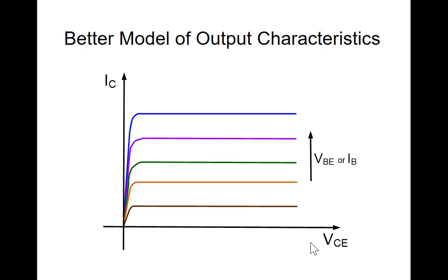So then, could you also use a MOS transistor as a current amplifier? No, because you would need the BJT for it. We can trick a MOS transistor to act like a current amplifier as well. We'll talk about circuits that do that later, but there's no current that flows into the gate, so you can't amplify a current that doesn't flow. Or you could think of a MOS transistor as having infinite current gain if you wanted to.